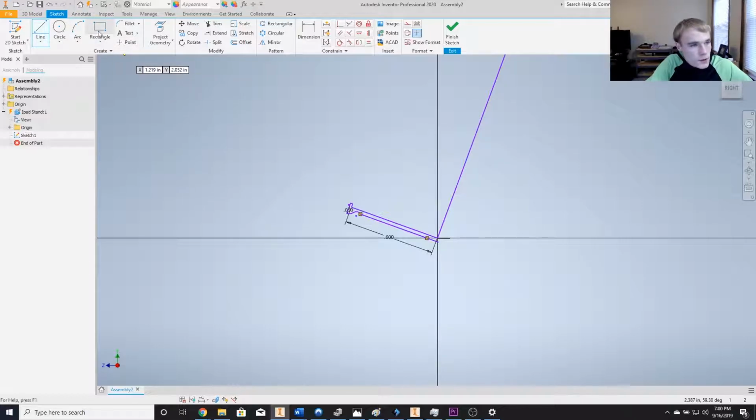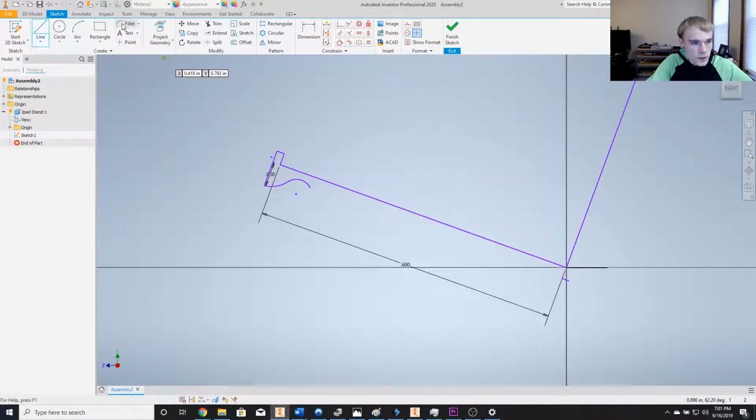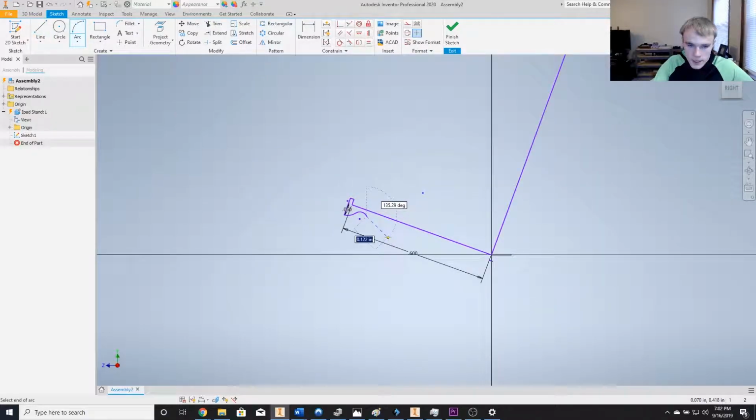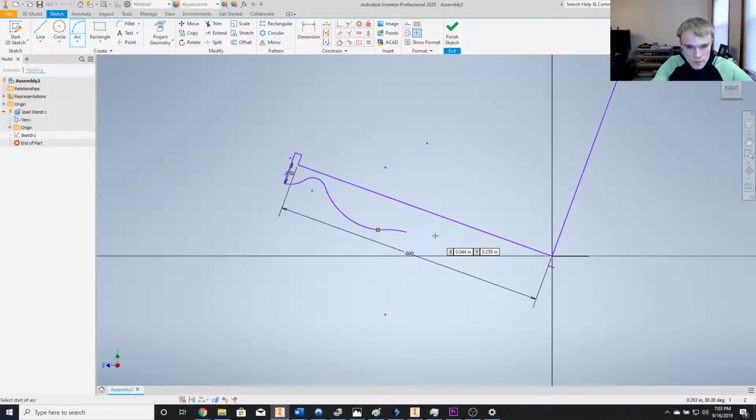Okay, I've got a plan. So what we're gonna do is I'm gonna trim right here and right here. I'm gonna delete those two lines and we're going to make another arc right here. We're gonna do the same arc deal, not nearly as far though. Something more along like that. Make it nice and tangent. And if I can get this to smooth out, I'm going to, but I don't have much faith. Much better. There we go. Much less abrupt. We're going straight back from there.